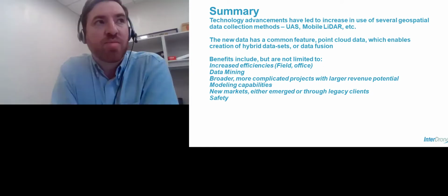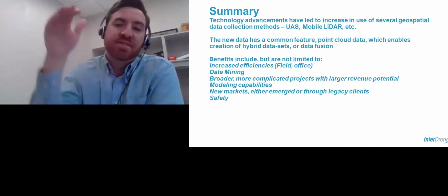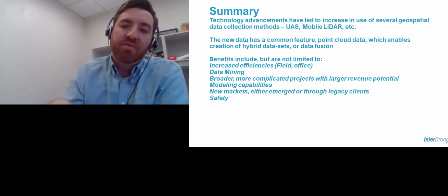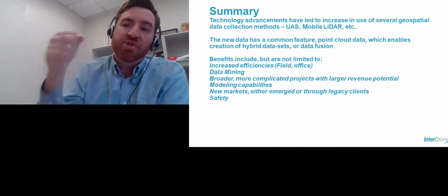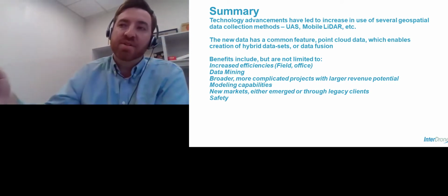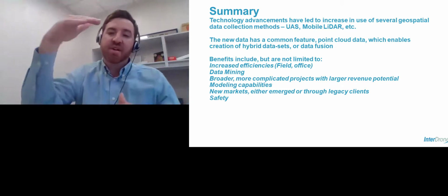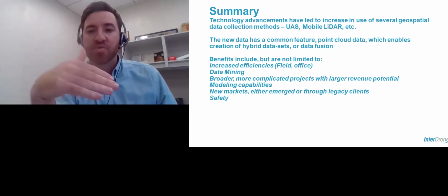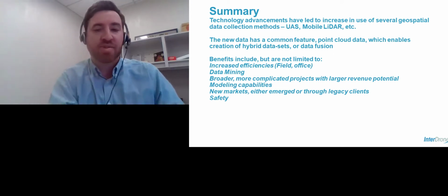So that bathymetric system we're using right there has a GPS sensor at the boat, and it's essentially using sonar to find the bottom, calculating that difference and giving us a conventional shot. As the boat's moving around, it's taking a timed shot every couple of seconds, calculating the difference between what it would hit, almost like a fish finder type tool, and applying that difference to the conventional GPS system like we would do on the ground. I don't know if I'm answering that question well, but.